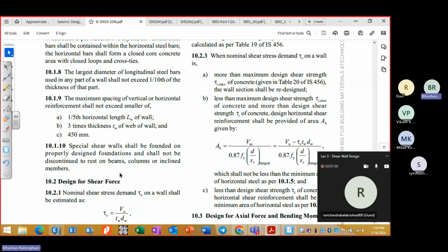for special structural walls. Sir, even a transfer slab is also not recommended, right? Not a transfer girder, but a transfer slab system. No, a shear wall cannot be on a slab, no? I have never seen that. No, sir, a transfer slab has a depth of around 1.8, 2 meters, like that. That is a transfer girder only. Okay, okay. So that is not recommended basically.